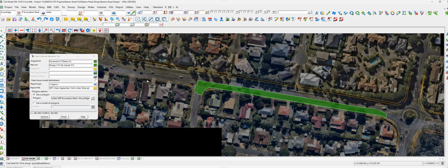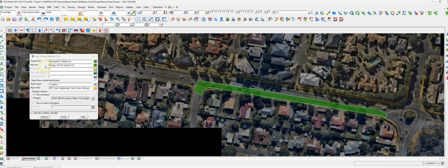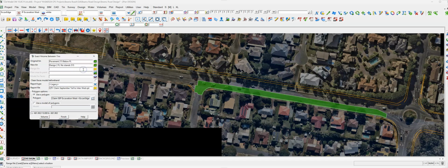Now, what we can do now, I might as well continue, is looking at range files and painting, or they call it painting, but essentially plotting out solids and colours for your cut fill ranges. So a range file, I've already got a few made. We'll make one from scratch, because if you're in a new 12D project and you're not working off old ones, you'll have to create one. So in this instance, I'll do a simple cut to fill one.